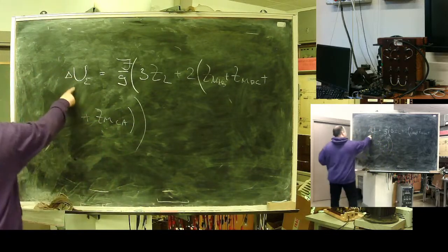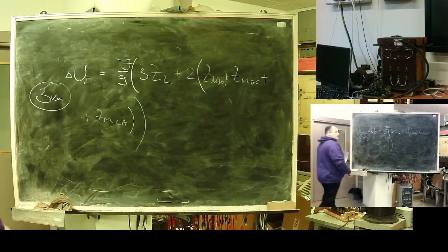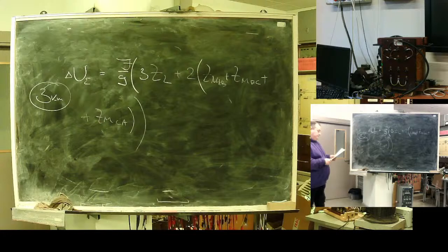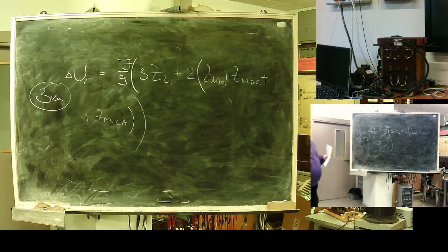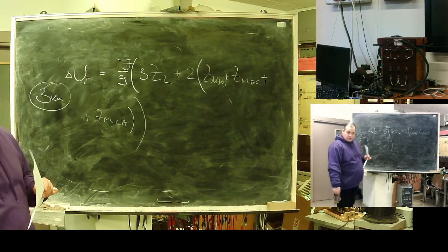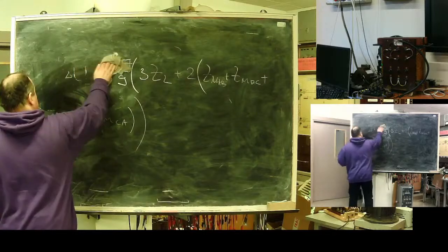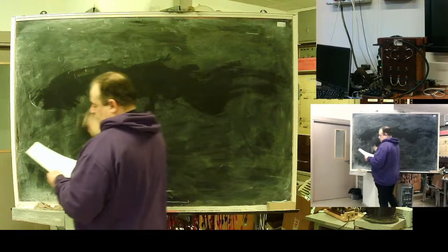Note, this is not for 1 but for 3 kilometers, for the whole line. Now I can get the zero sequence resistance for 50 Hertz, since I know both self and neutral inductance, or whole resistance, I also know the active component.